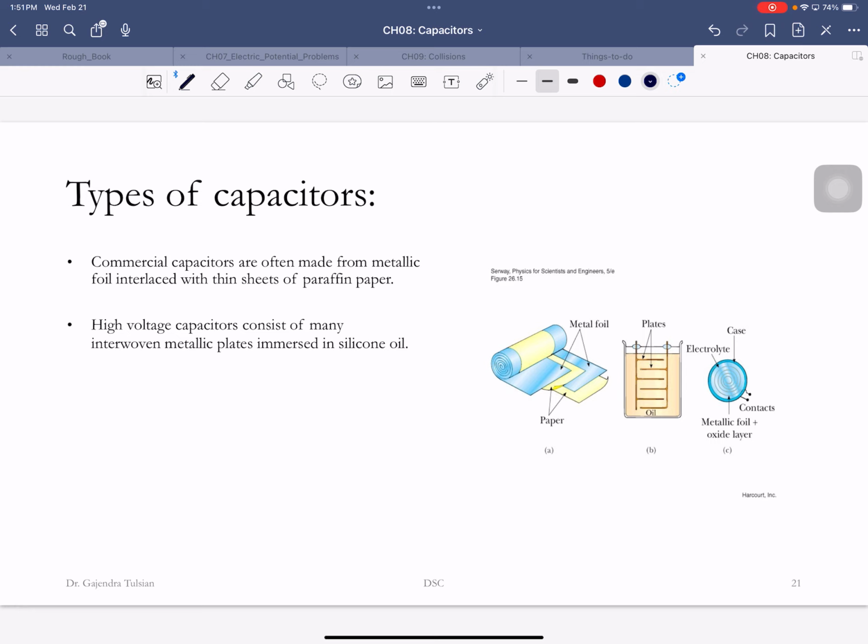All right, so here is the parallel plate capacitor. Now the capacitance is epsilon naught times area divided by d. This is with an air-filled one, and if you put a dielectric between them, that's the capacitance. If you want larger and larger capacitance, you could increase the area. You cannot decrease the distance between them too much, because the closer they are, the more likely they'll spark. Anyway, there's a limit to that.